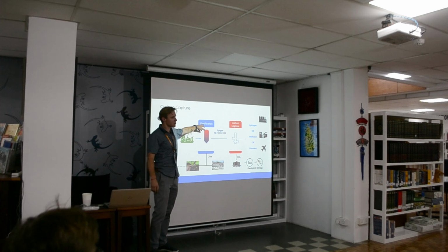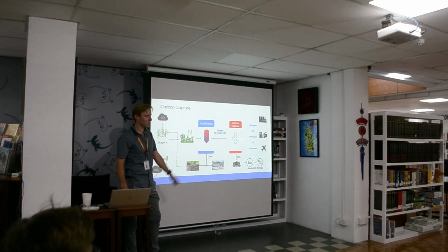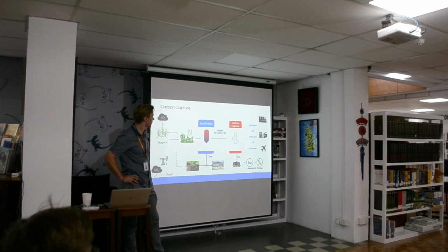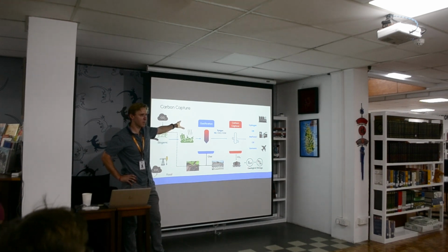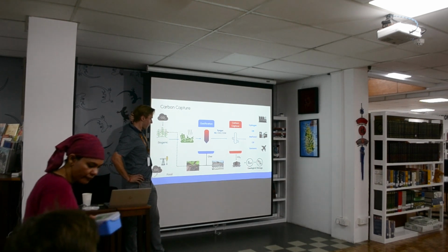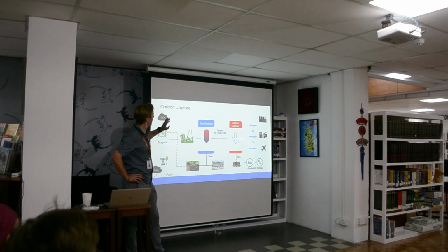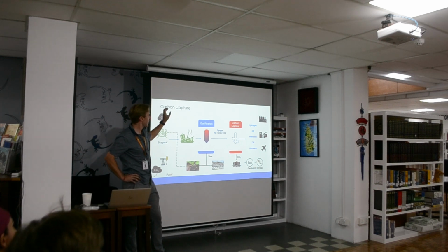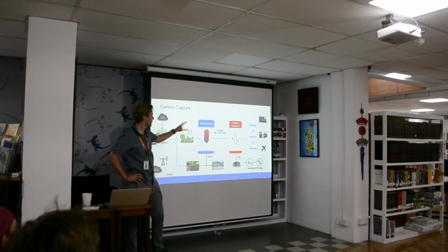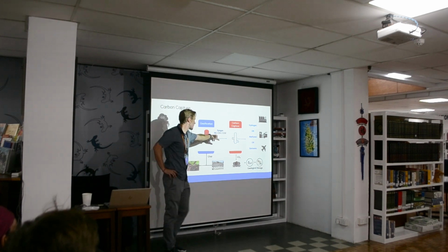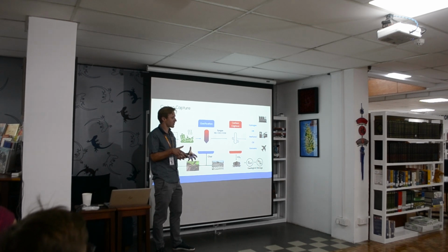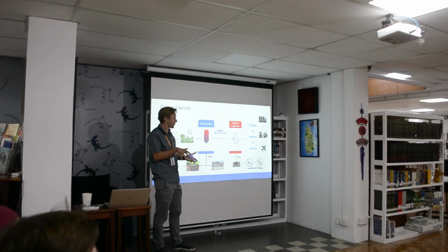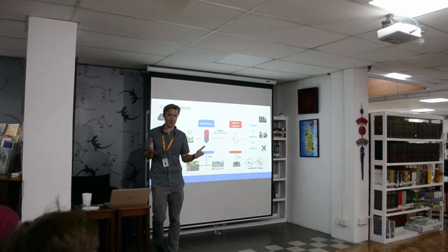Now, you mentioned the CO2, you have an opportunity to capture carbon, focusing on the gasification step instead of the other processes of consideration. Because this is the one that I know about. This is the kind of technology I've worked on for the last 6 years. The carbon capture process is a great opportunity when you use gasification, because the CO2 is already separated from the gas at pressure, so it's quite small volumetrically, so it's quite easy to process compared with an exhaust gas from an incinerator.